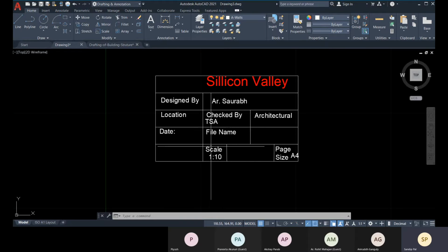Attribute is needed when we generally store our alphanumerical value, when those values are variable and we store it with block. So then we will create with attributes. So that is all about your attributes. Now suppose you want to hide all the attributes available in your project. So for that, ATTDISP, attribute display, is the command.